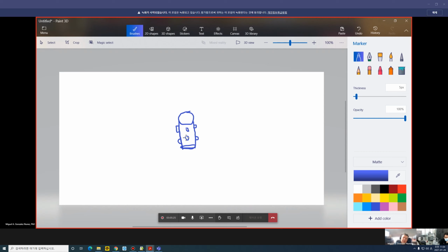And you use only the high vacuum silicone grease? Actually, first of all, when we use vacuum grease, we cannot attach the sensor directly on the surface of the granite specimen. Granite absorbs the vacuum grease.